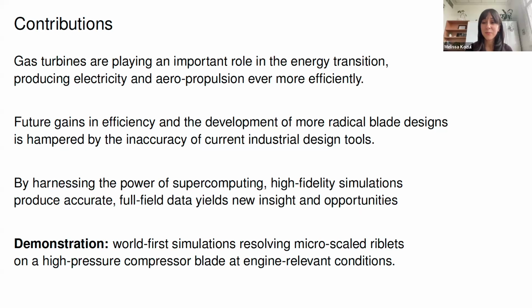consistent. Yes. So we saw that the riblets were able to... The riblets reduce drag when it's a turbulent flow, but when it's a laminar flow, it could provoke transition. Yes. But you saw it was also dependent: the flatter riblet didn't do that, but the sharper riblet did. So it could be used for transition control.